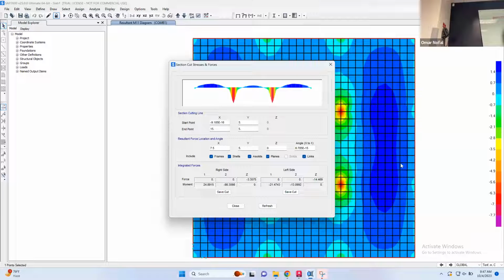So what we did with modeling the slab is that we made a line in the middle, not the whole thickness. And we made a line in the middle of the column, something like this, right? But the actual one is something like this. So what we do is we go 45 degrees, something like this. And if you went 45 degrees, this is about d/2 from the thickness of the slab. So this is where you should take the bending moment for the slab.